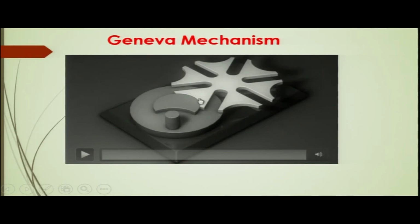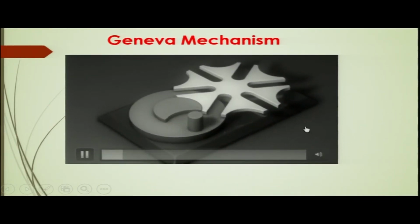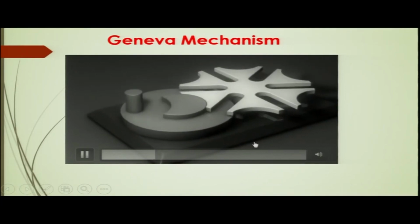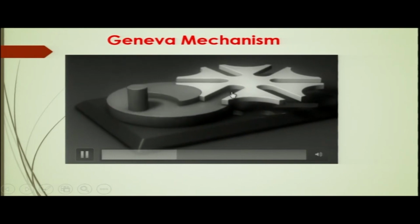This is the Geneva wheel, and this is the pin. The pin is sitting on this disc, and the disc rotates continuously. While rotating, the pin goes inside the slot of the Geneva wheel and comes out, and during that movement, as you can see, there is one indexing of the Geneva wheel. As you can see, it is entering and coming out, and in that case it is moving from here to here.